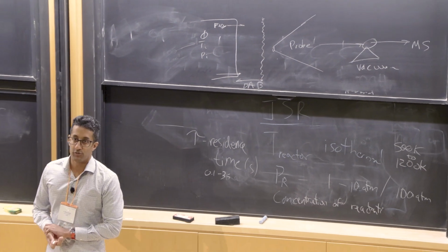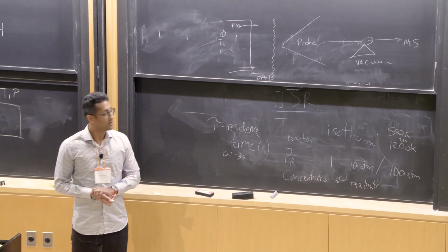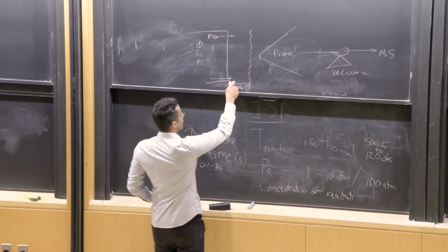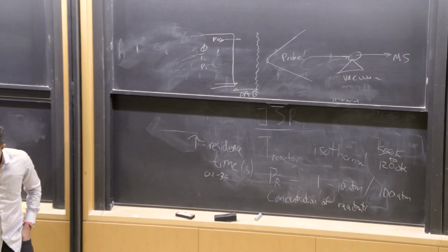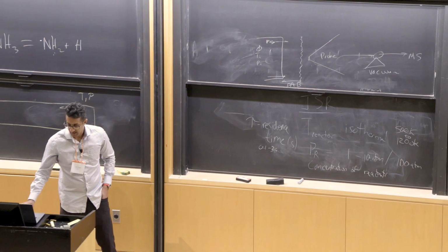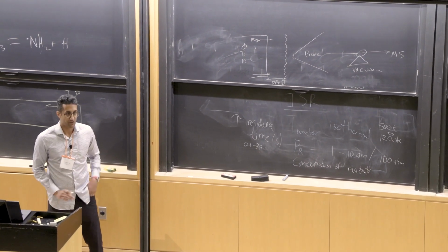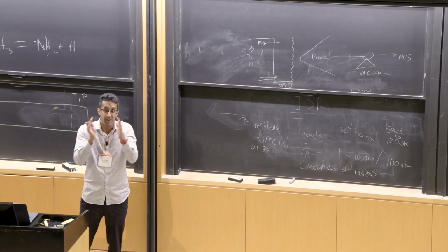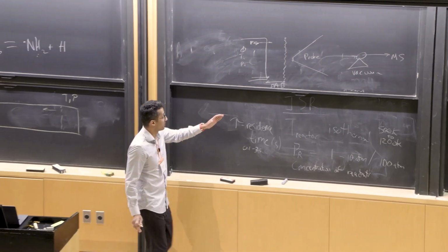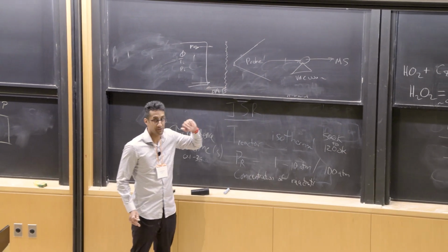So one advantage of doing this experiment at low pressure is you can get more resolution in distance of these different curves, right? Like temperature, species concentration, they'll become broader. At high pressure, 1 atmosphere, these things must be very narrow. And the flame will sit much closer to the burner surface.